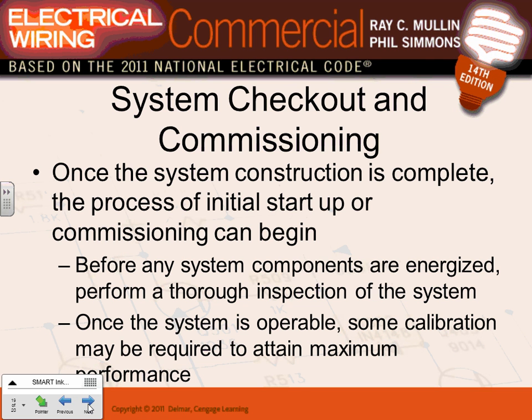I'll show you in a list in a second here. When you finish your system, when you build your system, there is a commissioning. They call it commissioning. Before your system, you have to go check all the connectors are there, all the disconnects are labeled, all the wires are stable, and all this good stuff. So you do commissioning in the building, and you go readjust your interactive inverter.